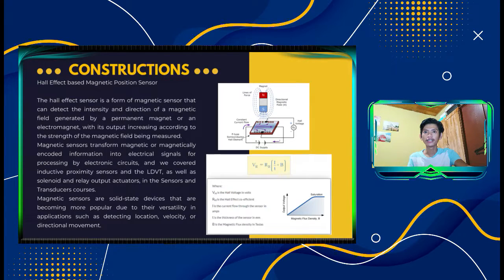Linear or analog sensors generate a constant voltage that increases with a strong magnetic field and decreases with a weak magnetic field. In linear output Hall effect sensors, as the magnetic field intensity increases, the amplifier's output signal rises until it saturates due to power restriction. Any increase in magnetic field will not affect the output but saturate it.